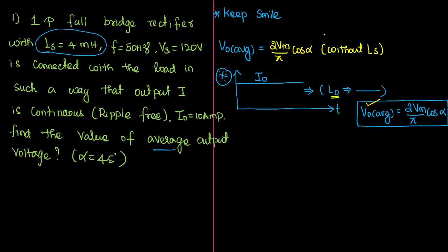So in this case, directly you can substitute the value of alpha. Alpha they have given how much it is? Yeah, alpha is 45 degree. Okay, sir. And maximum voltage, what is the value of maximum voltage? See, if you observe, given it is source RMS voltage, yes or no? Always by default, given it is RMS voltage. If given it is RMS voltage, how will you calculate the Vmax? We all know Vmax equal to square root 2 times Vrms.